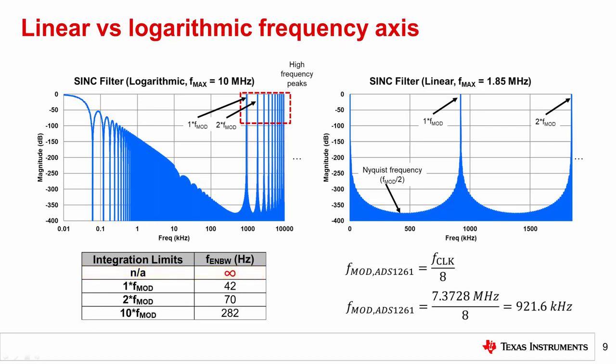From a mathematical perspective, this is due to the fact that the integral of the sinc function from 0 to infinity does not converge. How do you continue this analysis given the sinc filter's infinite noise bandwidth? To move forward, you just need to set limits on the integration.